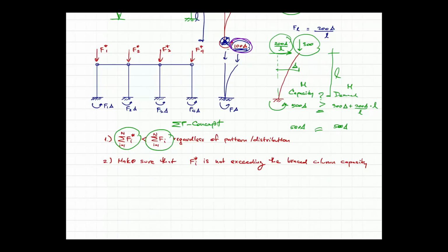So we are still subjected to number 2, but it is good enough. We have the leaning column and the other columns in the same system. If they are still not hitting the capacity, they still help stabilize the column that is in trouble in the same story.